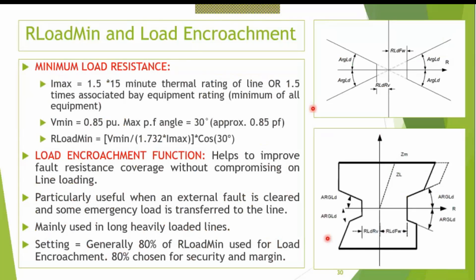Okay, this is the load encroachment characteristic as seen in the relay. What this load encroachment characteristic does is that you can increase your zone 3 resistive reach as much as you want, without having the limitation of load tripping in real-time load.